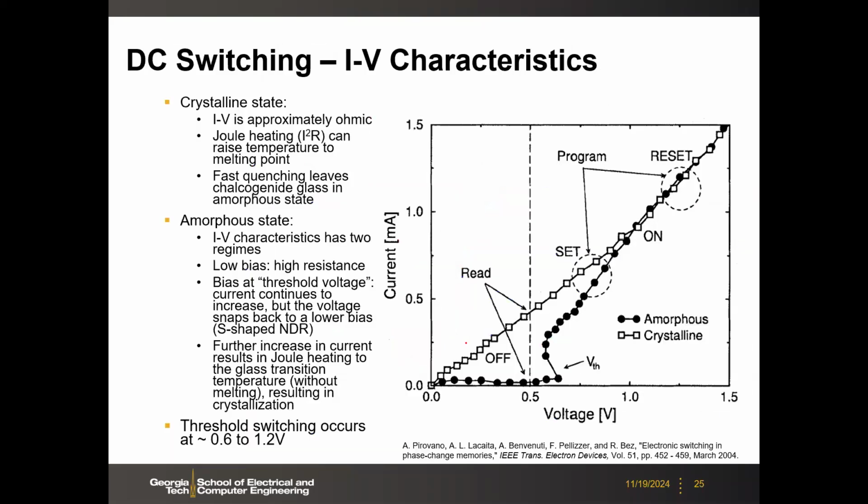So here, if you measure the IV characteristic in the quasi-static sweep, typically this is not the real way to operate the memory, but if you want to, you can still do it by the quasi-static IV sweep. In this case, I think you sweep the current instead of the voltage, because you have this snapback.